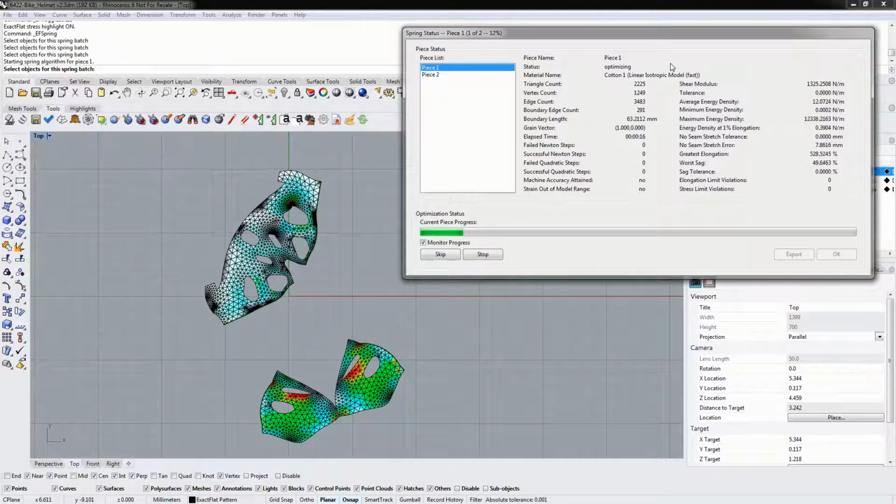So the symmetrical nature of the shape may not be fully restored, and that has to do simply with the triangulation of the mesh. For this piece here, we can see that we've got local zoning of the triangles up here, which may indicate some kind of defect with the original 3D model. This may inhibit the ability of the optimizer to fully resolve the shape here.